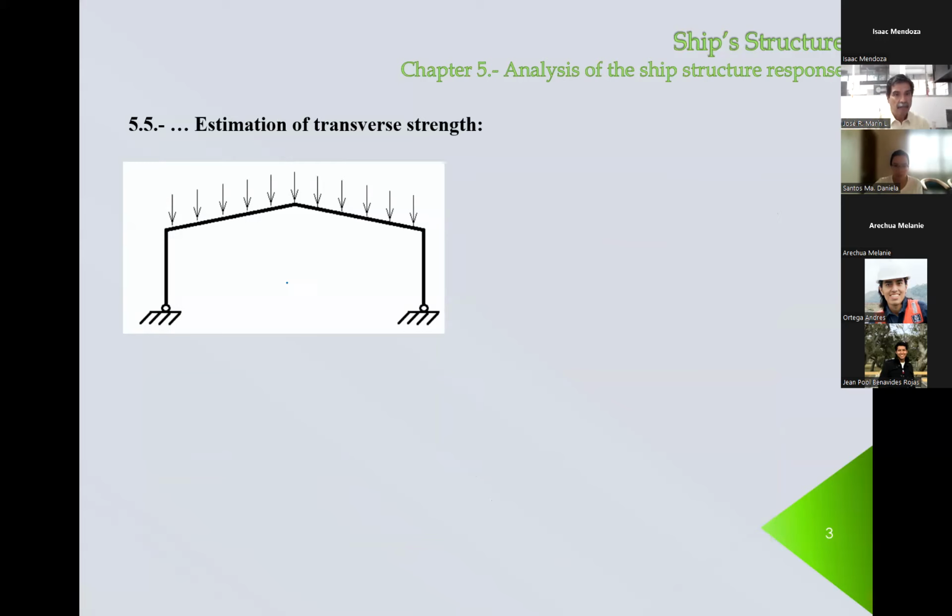Okay, tell me, what do you understand by this? What does this mean? Ms. Valdez, what does this mean to you? A simple support. And in boundary conditions, what does that tell you? Deflection is 0 and bending moment is 0. Exactly. So this point cannot move in the direction. In this case, it would be V. The W is also going to be 0.